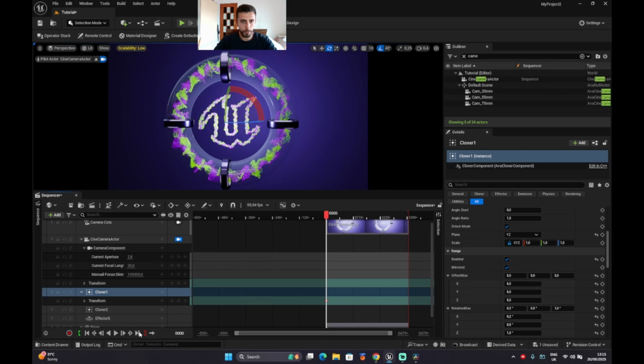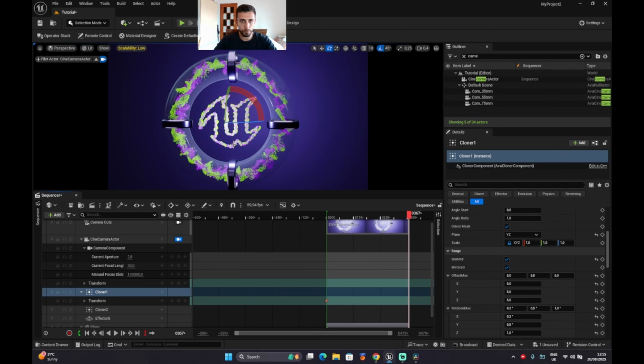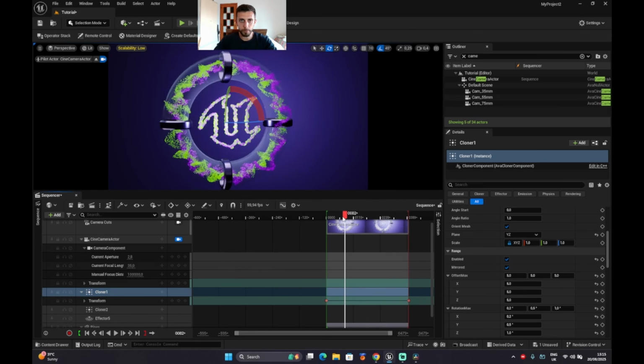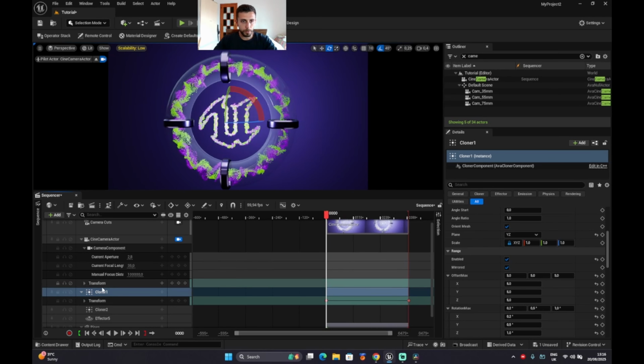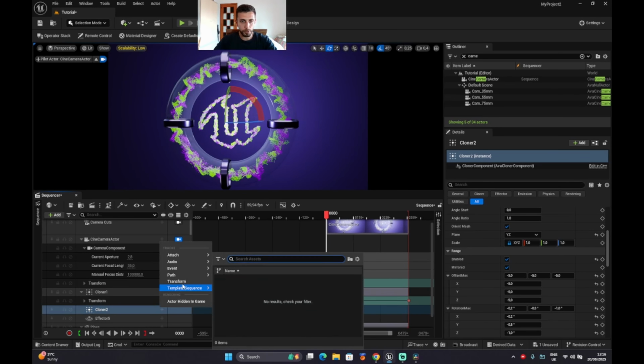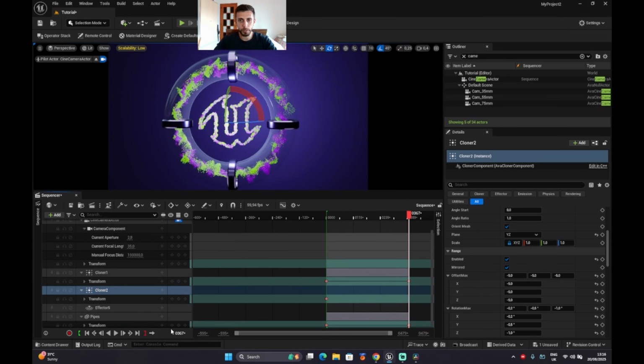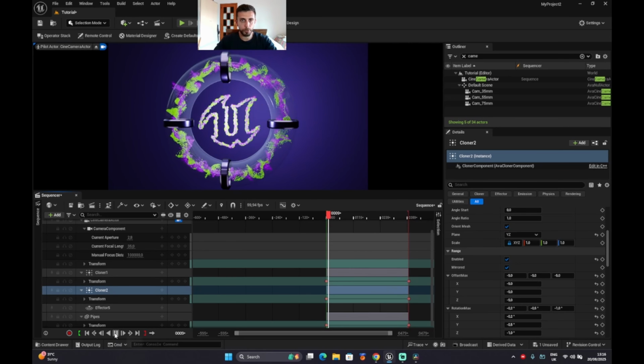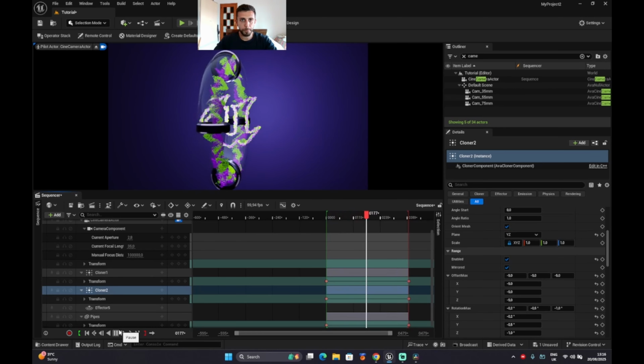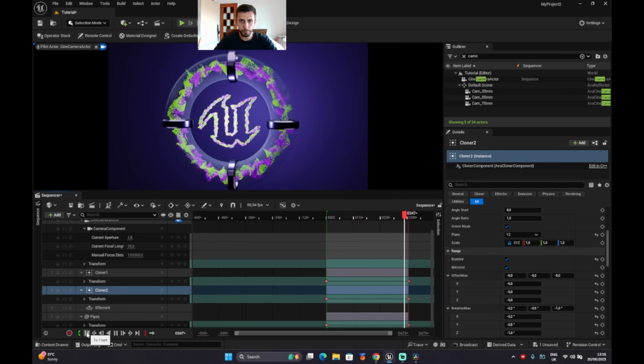Keyframe. Go to the last keyframe again. 180 degrees and keyframe again. Yes. Cloner 2, same thing, add the transform track. Keyframe the initial position, move to the last frame, and rotate this 180 degrees, keyframe again, and now we should have all of them moving together. That's perfect.